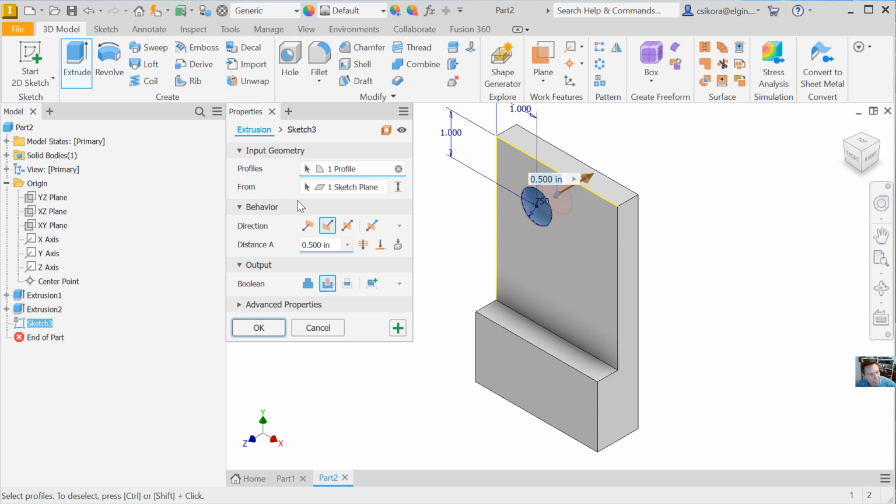But let's go ahead and, one other thing. There's something called design intent, and with parametric modelers like Inventor, SolidWorks, Creo, they all are kind of the same. You want to be sure that you make the model to where it's easy to be edited for the next person or even yourself later on. And there's certain, they're not rules, but they just are helpful hints. So for example here, we see that this is going 0.5 deep, which is the thickness of the model currently, but maybe there might be a change that comes down, and change always occurs in engineering and design.